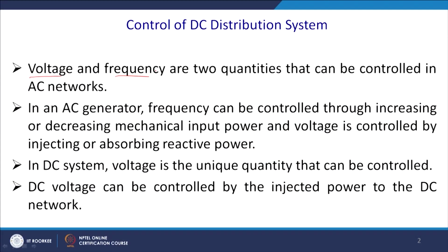As we know, in the case of the AC microgrid, we have PQ control and V-f control, and essentially this leads to control of the two quantities, voltage and frequency. Generally, when a microgrid goes into islanding mode to manage its demand, frequency drooping will occur, and with that the voltage also changes, and thus they want to maintain the V-f control.